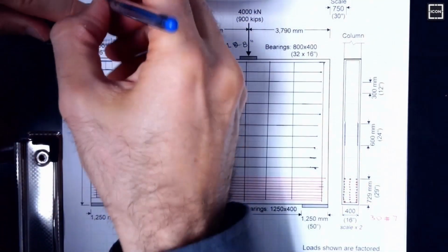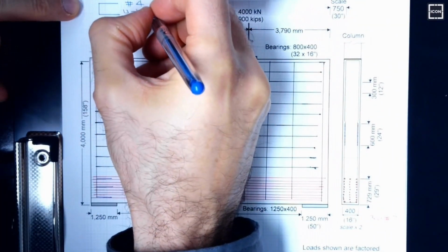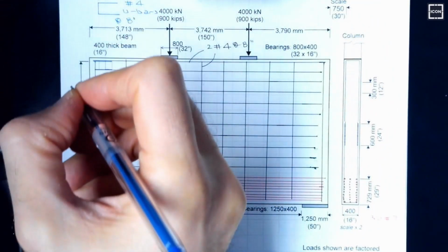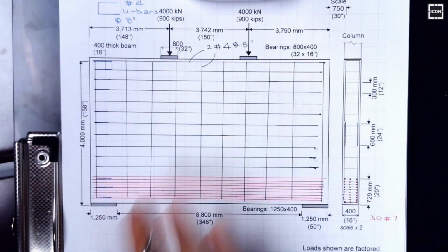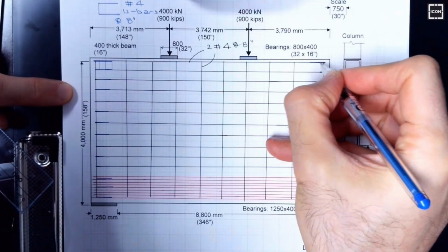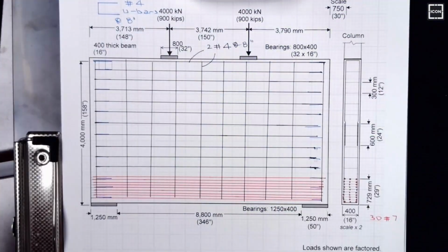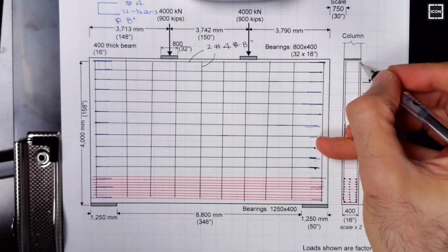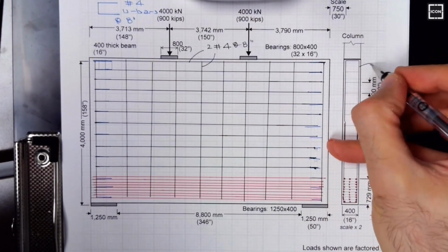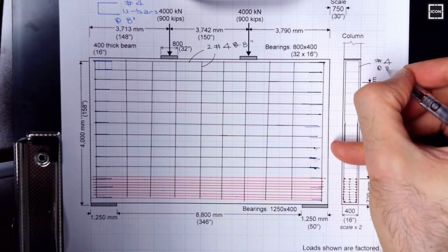So what I'm putting is number 4 U-bars. Again, you can use the same spacing, 8 inches, if you want to prevent edge splitting. It has nothing to do with strut and tie model, but this is just a good design practice. So again, you can put it, you should put it on this edge as well. As you can see, crack control reinforcement is such a narrow section, so it looks like I used 2 U-bars. So this is the crack control reinforcement, number 4 at 8 inches.